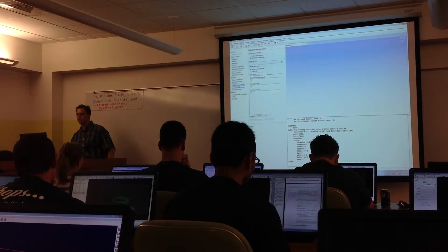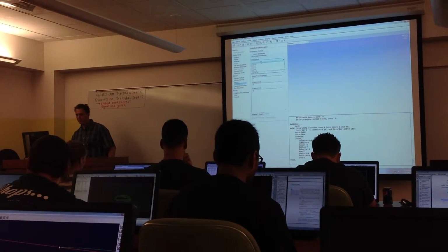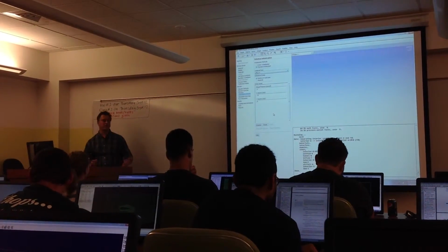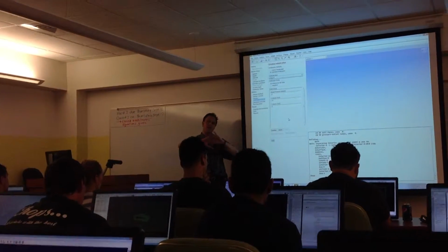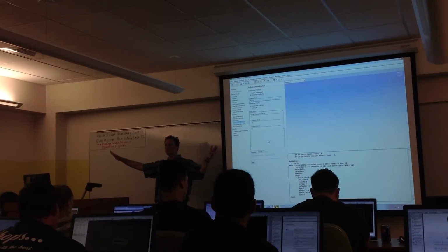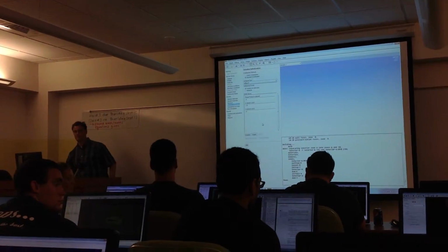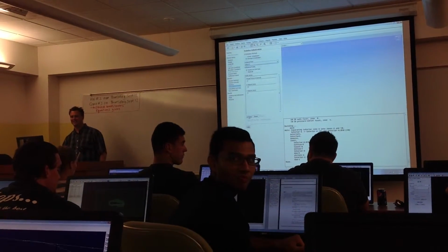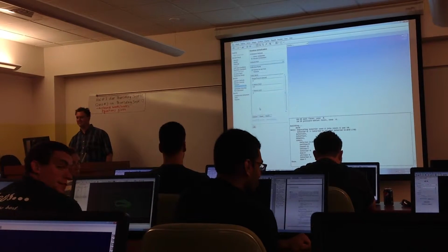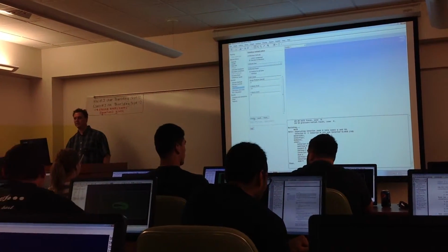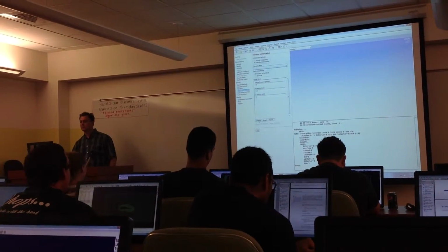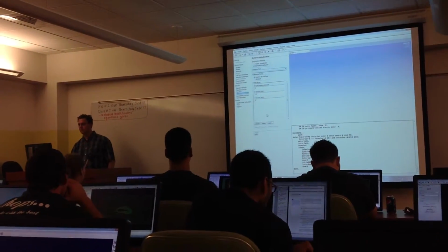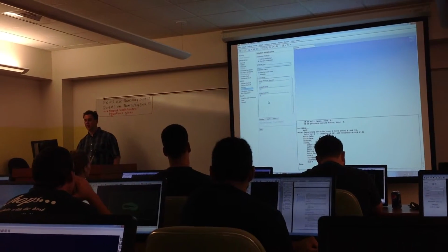Ready to initialize the solution. You compute that initialization from the inflow conditions. That means it's going to take your inflow conditions of 15 meters per second and just apply that to your whole grid, and that's where the solution is going to start. Okay, press initialize. Which it did. Good job. Very fast. The visualization is so fast because the grid's so small.